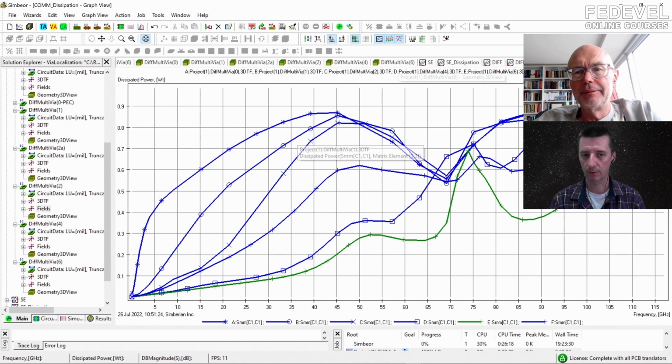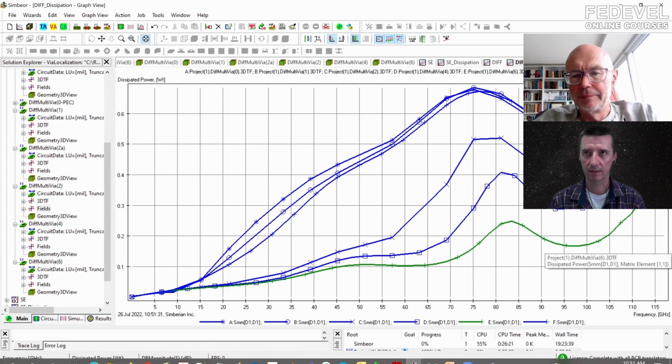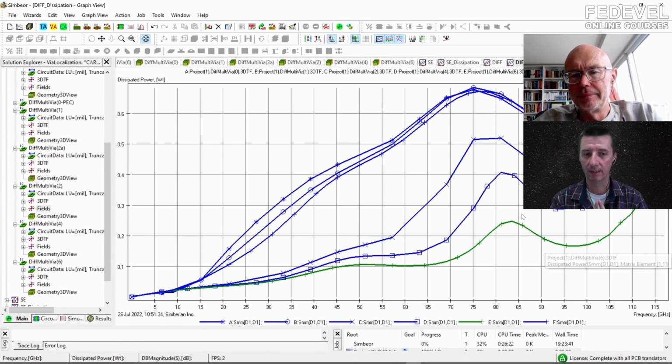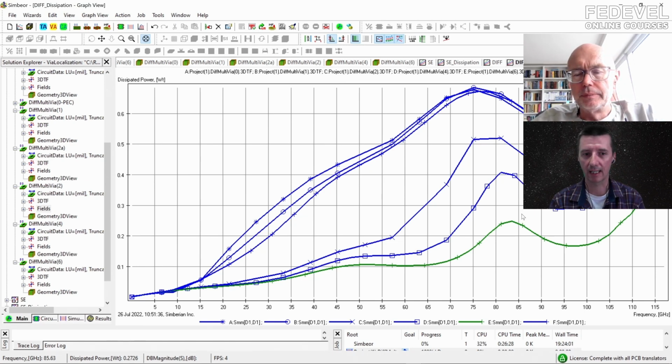So as you said, if we would only have like two straight differential pair lines, then that would be perfect. But because of all the bending and all the phase adjustments and everything, there may be some common mode difference between these two negative and positive signals, and that's still something that can make problems if we don't use the stitching vias in lower frequencies.